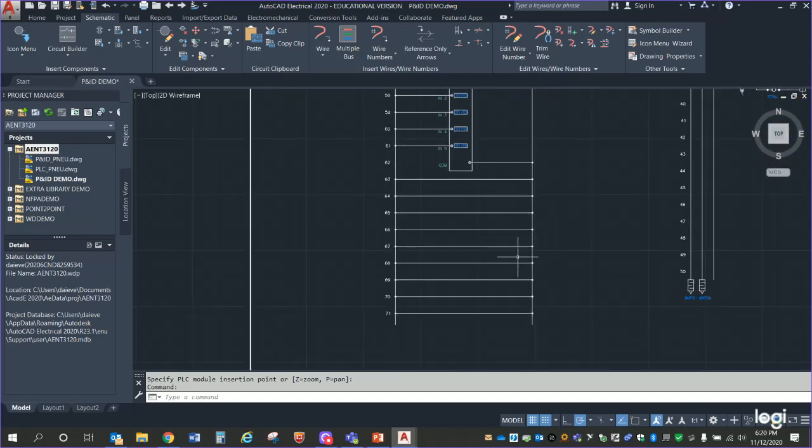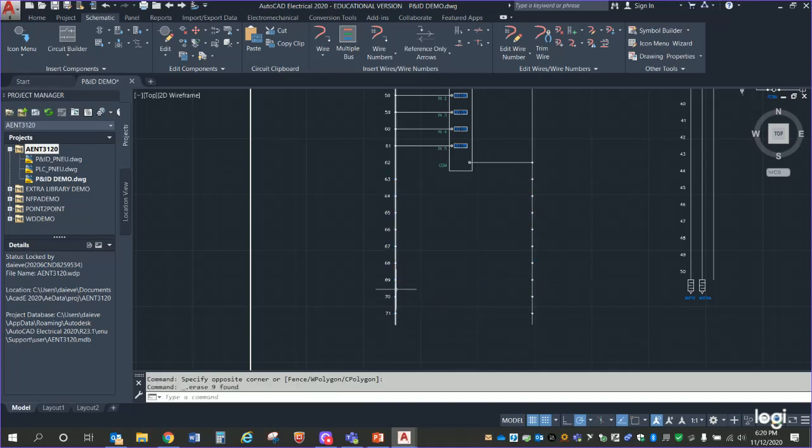Now, this is the thing I love taking points away the most. What is it, guys? The extra rungs. I absolutely hate the extra rungs. So go ahead and highlight those, select them. I'm also a fan of making these rungs the right length. So another place where having that snap tool on is handy, so you stay in line.